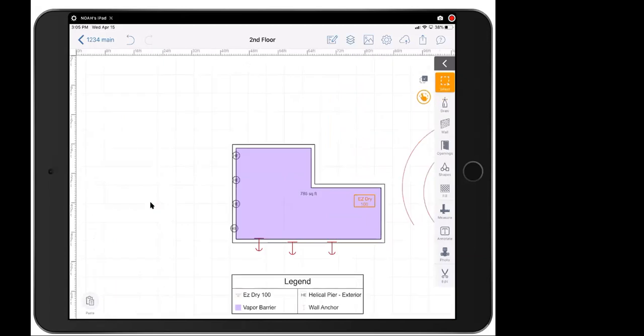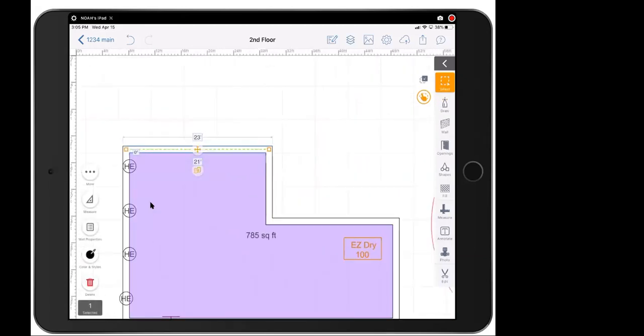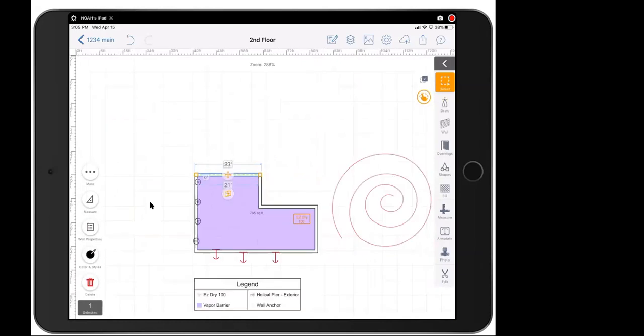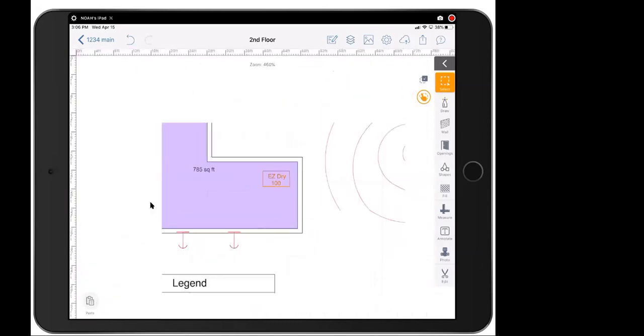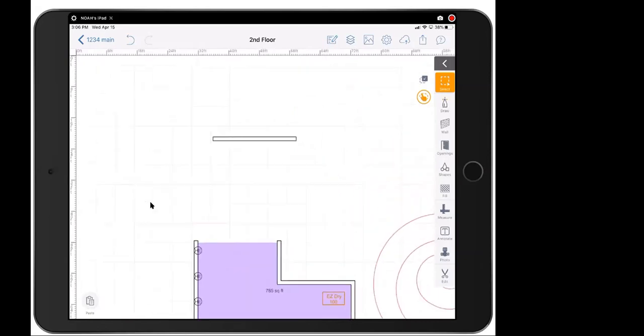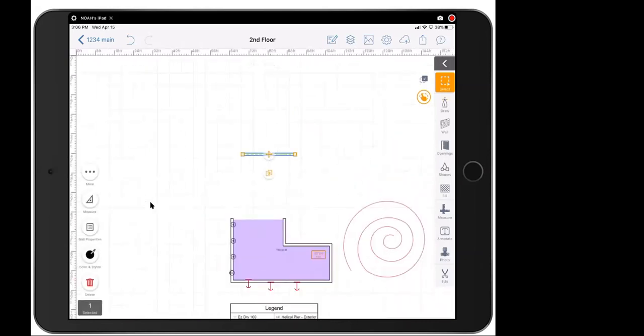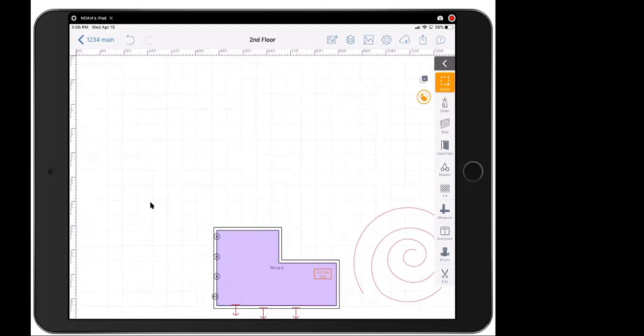So it might be helpful to zoom in, select the object you want, and then zoom out to actually move it. If you're really fluent with ArcSite, you're going to be constantly zooming in and out to select different pieces or draw them in, and then zooming out when you're all done and panning to a different part of the drawing. So you really want to get in the habit of doing that.